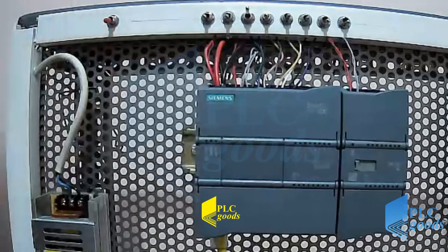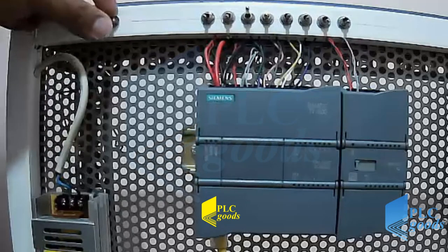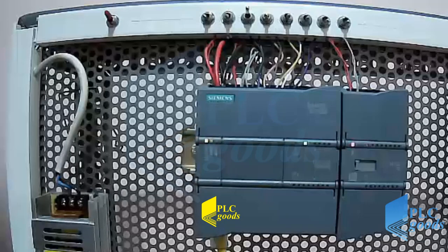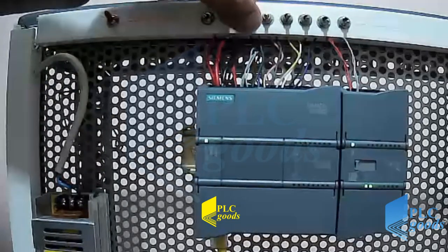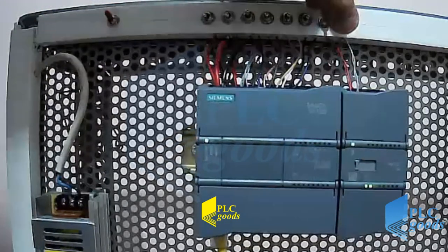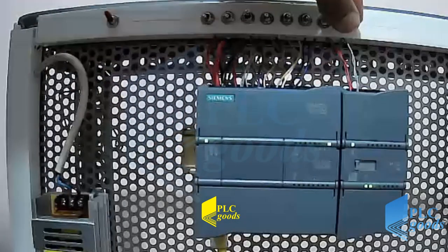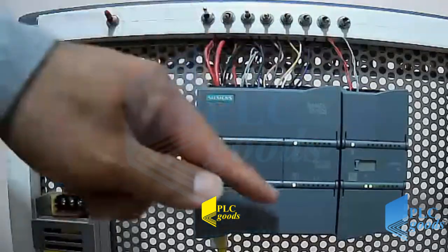Now, let me show you my equipment, and download this program to my PLC. First, the 220 volt AC is converted to 24 volt DC, by this converter. Then, my PLC can be turned on by this switch. Also, these 8 switches are connected to 8 digital inputs respectively. We can understand which inputs or outputs are activated with these LEDs.